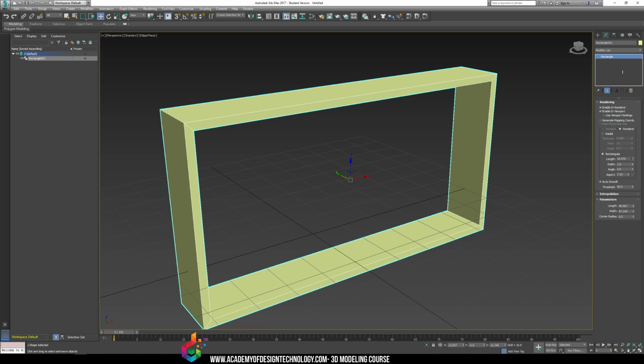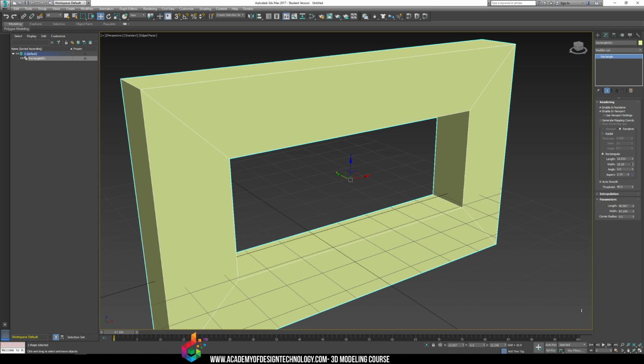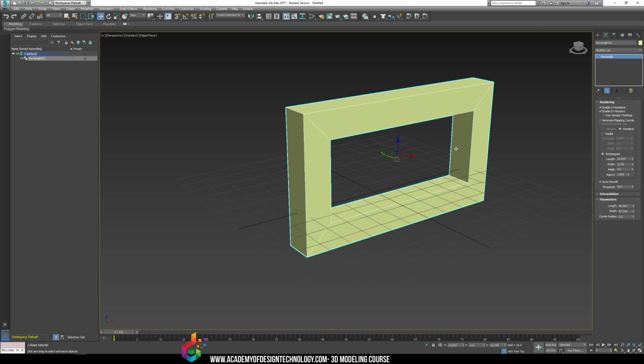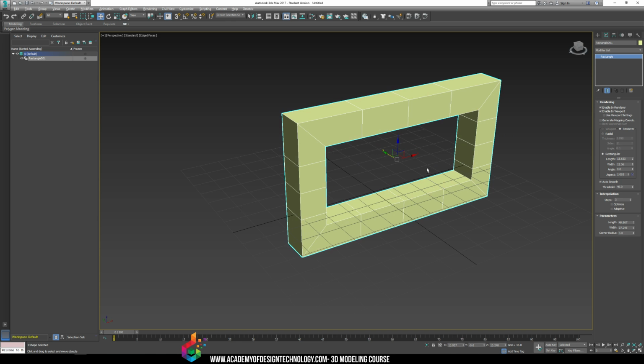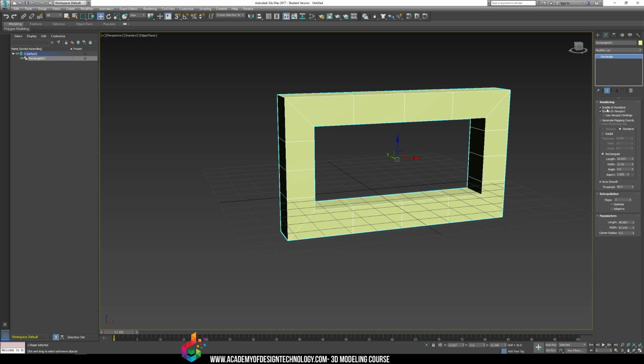I can also go to rectangular mode. If I wanted to create a window or a belt buckle or something like that really quick, why not just go to the rectangular tool? Instead of getting a polygon, extruding it all the time, I can just literally pick a rectangle and it creates a shape for me. I can then convert it to an edit poly and that's it. Away I go, right? No issues. And I can change the interpolation type if I need to, not optimize it so I get more polys. And then I can change the amount of steps if I really want more, as long as they work with the rest. So now I get this nice shape that has lots of edges that I can use and I can extrude from, which might work great for exactly what I need.